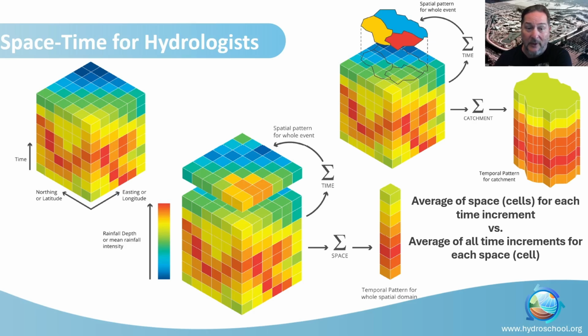Now, for precipitation, it's especially important to know how long we need to run this for, because different critical durations might have different temporal patterns, and the infiltration losses would affect each pattern differently in terms of the resulting flow rates. So you always want to run it at least long enough for flow to get from the furthest point upstream from the source all the way down to the outlet. So sometimes what I do is I'll just put in a constant rainfall and then check the downstream outlet to see when we max out the discharge. And that will give you a feel for the time of concentration and the lag time. And so I'll do that sometimes before I ever even put in any real values.